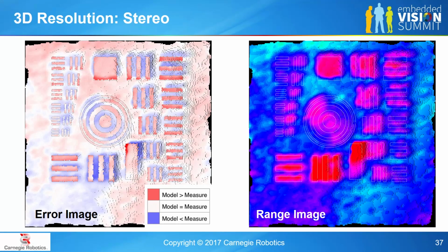You see first in the bottom left of the range image that the horizontal bars stick out much more cleanly and are much more accurate than the vertical bars. The vertical bars have a lot more smearing and incorrect returns between them. This is caused by two different things. One is that the stereo matching process works horizontally, so the edges of objects in the horizontal direction are less accurate than the edges of objects in the vertical direction.